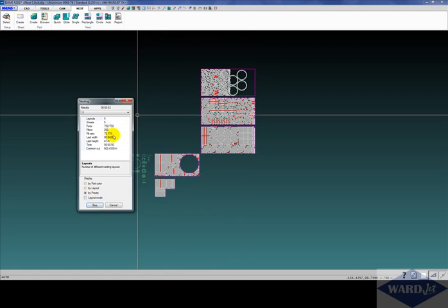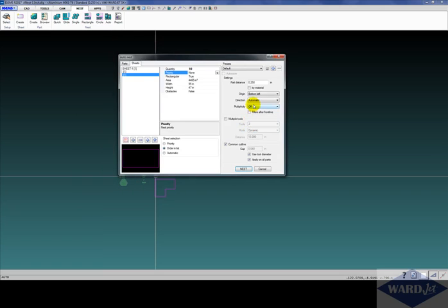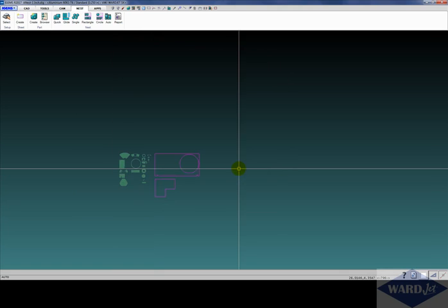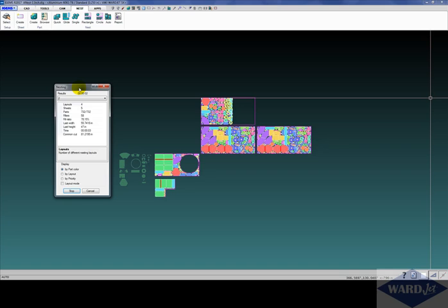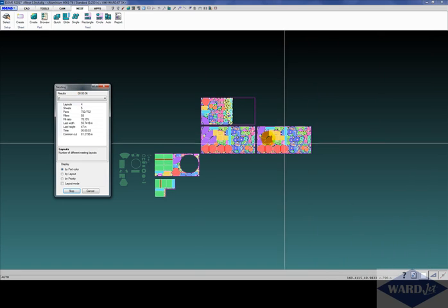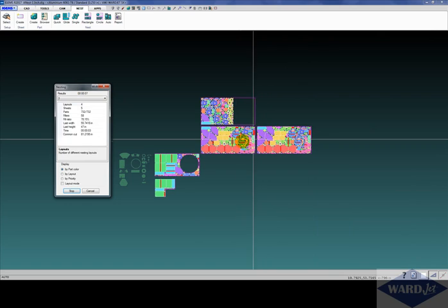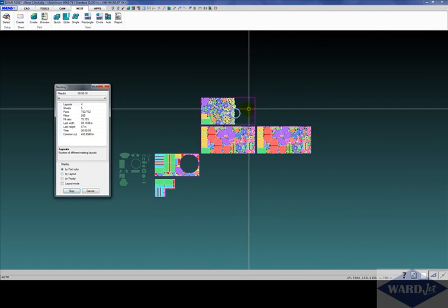If you had specified a higher priority of parts, you would see where those are in the nest. Layout mode will just kind of line up your different nests in one easy to see layout like that. So let's see, what are we up to here? About 73% right now. So if I just click on cancel and then go back and turn multiplicity on high and click on nest again, we'll see what happens here. So what it's got right now, these 2 nests are the same. And we'll just let this go for a little bit more and see what happens here.